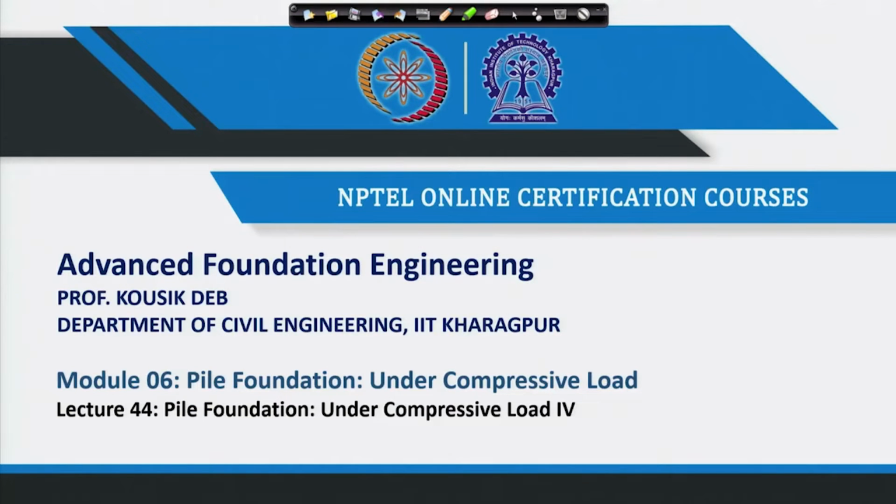So, last class I discussed how theoretically we can generate a load settlement curve for a pile. In that approach we divided the pile into a number of segments, and then for each segment we calculated the settlement at the center by assuming a tip deformation, and then we get the ultimate load carrying capacity P_U of the pile and the settlement of the pile at the top based on one particular assumed tip deformation.